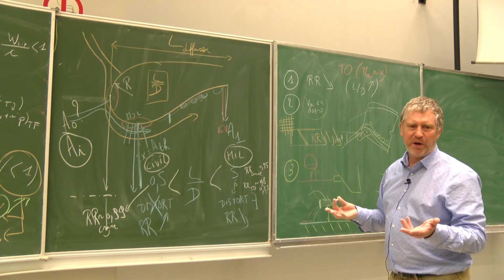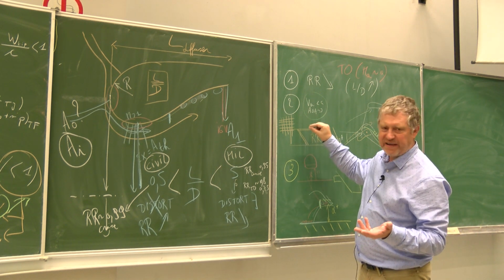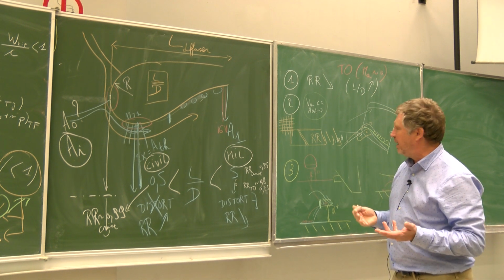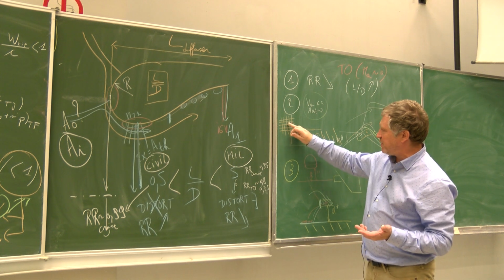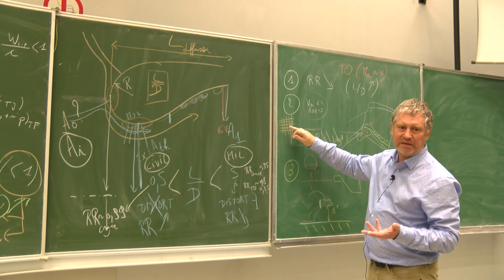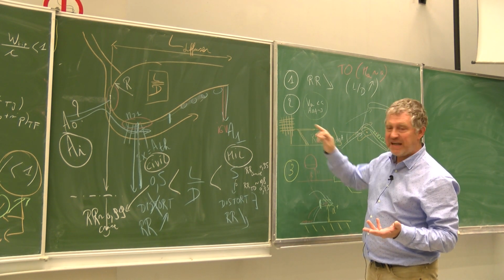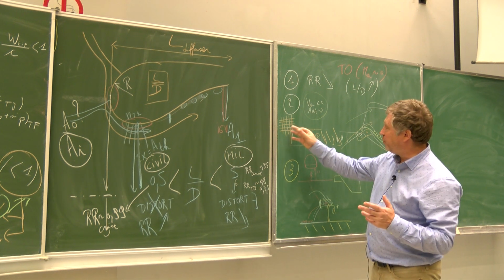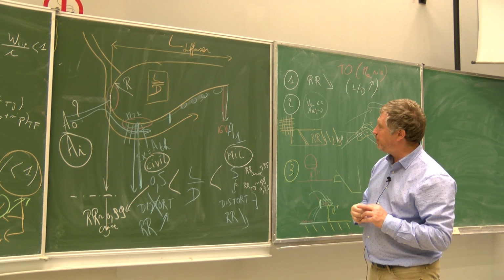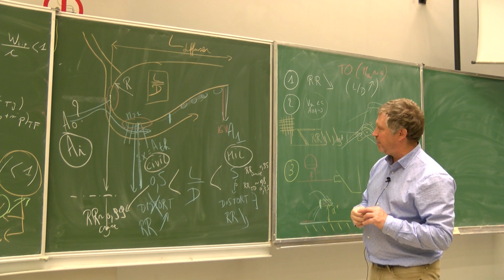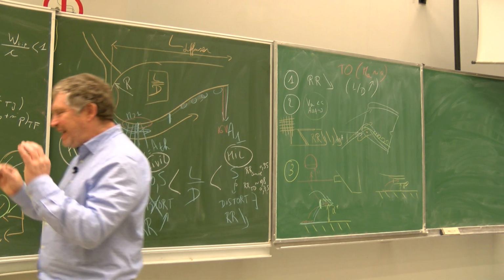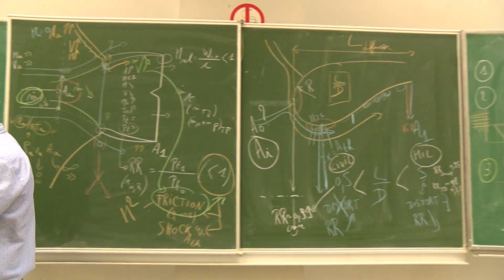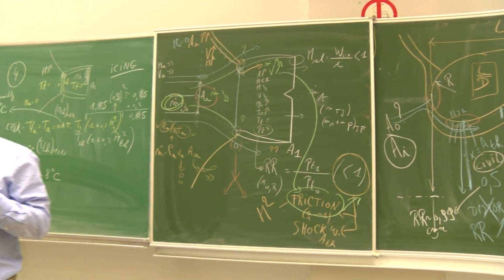You use the afterburning, and this is on the Sukhoi 27, on the Flanker, and it is not a problem because you have afterburning. The danger, of course, is that you could have icing on the filter, on the coarse grid that you are putting there. So you see that takeoff is not an easy condition.